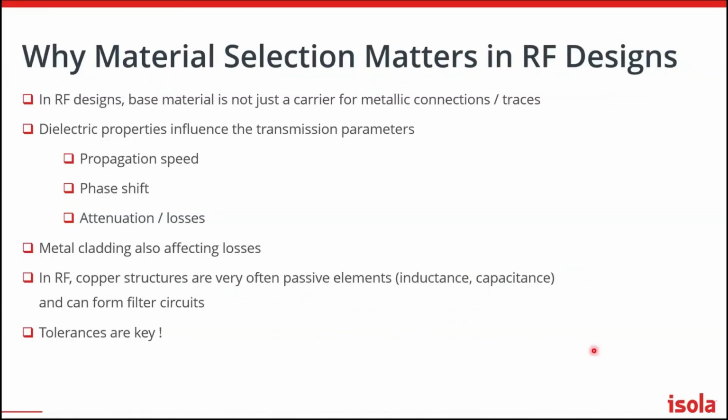The question of why material selection is so important in RF designs: the base material is not just the carrier for your transmission lines. It's much, much more. It's influencing your signals. It's influencing the transmission parameters like propagation speed. It causes a phase shift.